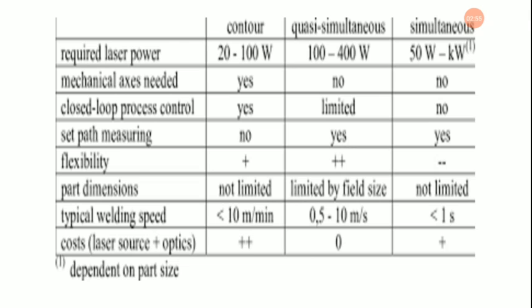So Taguchi's orthogonal array was selected for experimental planning. The experimental result analysis showed that the combination of higher levels of peak current, base current, gas flow rate, and lower level of welding speed and intermediate level of pulse on time and frequency is essential to achieve simultaneous maximization of penetration and minimization of face width and back width. The ANOVA is next used to analyze the results further.